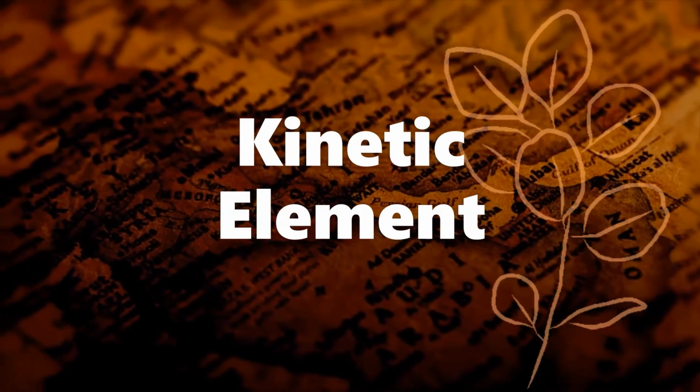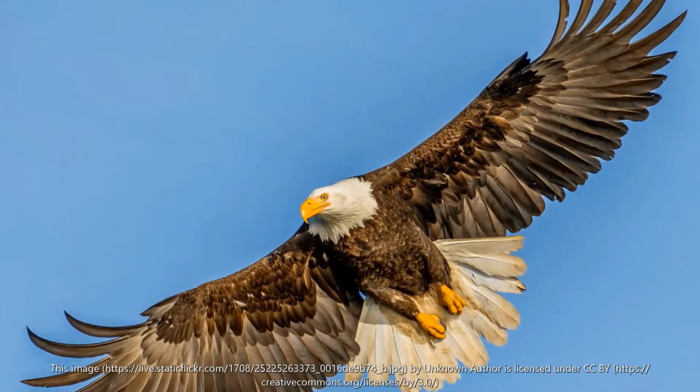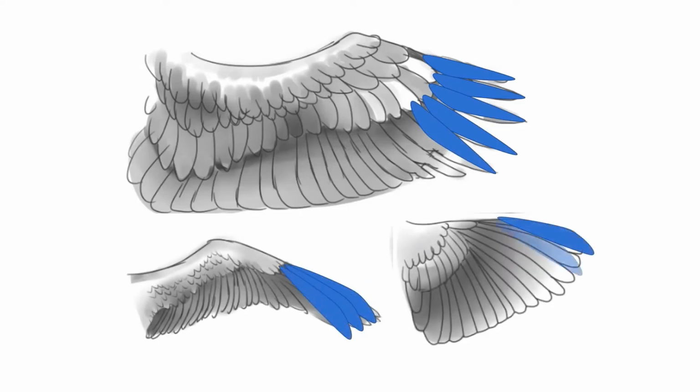Kinetic element design. The basic concept is inspired by birds' wing feathers that open and close in different positions. Based on that, we have developed a sliding fins system made from perforated metal to create shading. The system is controlled by sunlight sensors to manage kinetic element operation.